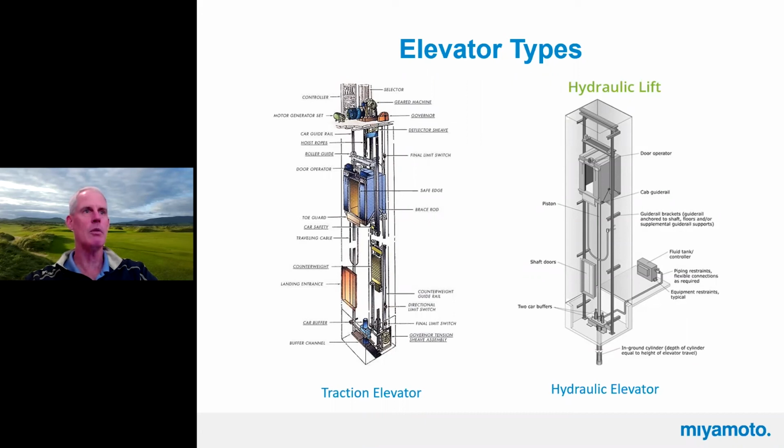Then the second reason is the steel guy can come and he can set that whole cage structure for the elevator shaft, and he walks away. And then the framer comes in, he frames in everything, and then they attach the guide rails to our support tubes, and then they're done.